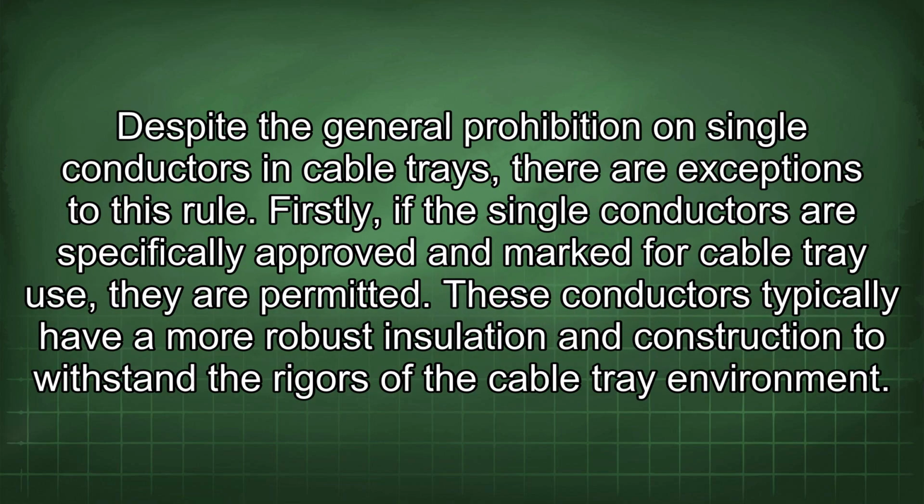Despite the general prohibition on single conductors in cable trays, there are exceptions to this rule. Firstly, if the single conductors are specifically approved and marked for cable tray use, they are permitted. These conductors typically have a more robust insulation and construction to withstand the rigors of the cable tray environment.